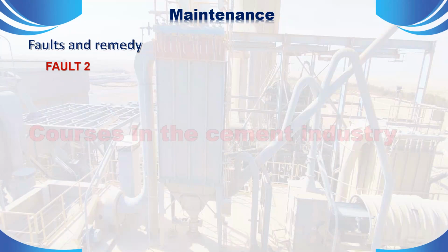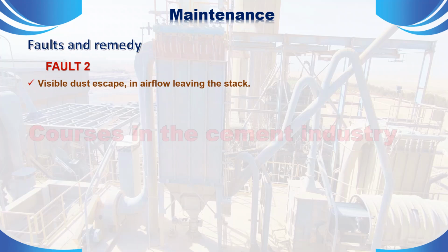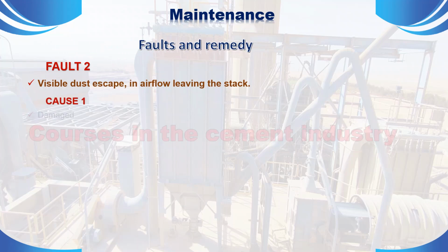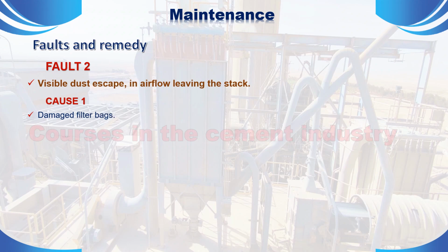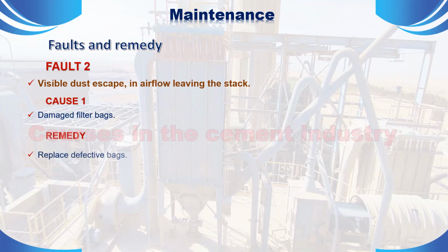Fault 2. Visible dust escape in airflow leaving the stack. Cause 1. Damaged filter bags. Remedy. 1. Replace defective bags. 2.